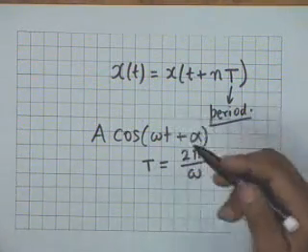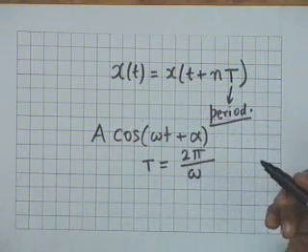To get a measure of a periodic waveform, you can display it on an oscilloscope. If you do that, then you get the complete picture. Another way of characterizing a periodic waveform which is a sinusoid is to specify capital A, the amplitude, the frequency omega, and the initial phase alpha. But if the periodic waveform is not a sinusoid, then you either have to display the complete waveform as on a CRO or take some characteristic parameters of the waveform.